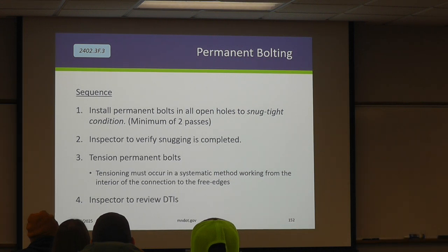So when they're using the gun approach, it's great because they just pop that gun around, it's at 100 foot-pounds, boom, boom, boom, boom, boom, go again, boom, boom, boom, boom, boom. Very consistent. We call it a precision bolting system, and we're really encouraging that of our contractors. So they snug it. You verified that they've snugged everything.